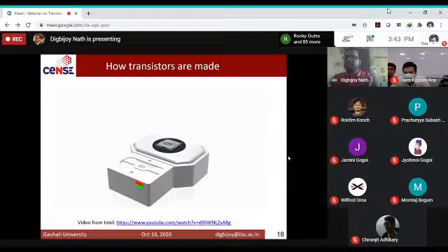Now you might still ask, how did they make these 1 billion transistors so precisely? You remember that mask I was talking about, where you shine light and then project, the photolithography. In the mask, actually, you can have billions of transistor patterns that you shine light on and project onto a wafer. Then that's how you proceed. So that's a process called photolithography. You transfer the imprint from one layer to another layer.